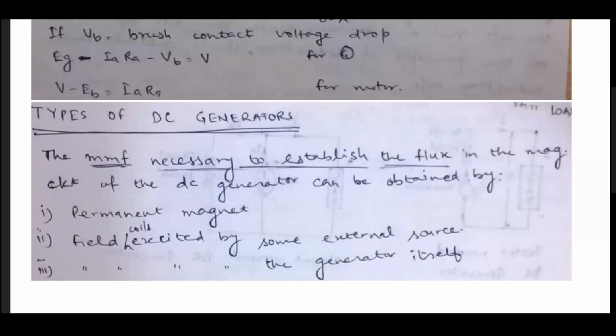So when we give this electricity, say V voltage is given by us, then if we subtract the armature drop here as well, that resultant EMF, here denoted by Eb, is known as back EMF. So that back EMF appears across the armature of the motor. Okay, is this clear?